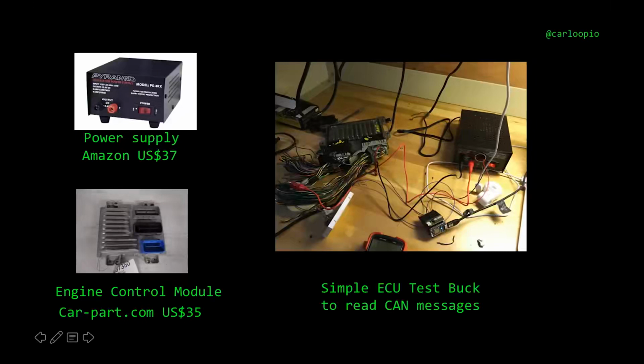Basically, you connect on one side a device that reads data, and then on the other side you connect a scan tool, so you can actually send a request, like, I don't know, what's the RPM, and then you'll get it back, and you'll see what request was sent and how to capture the message back as well. Does that make sense?